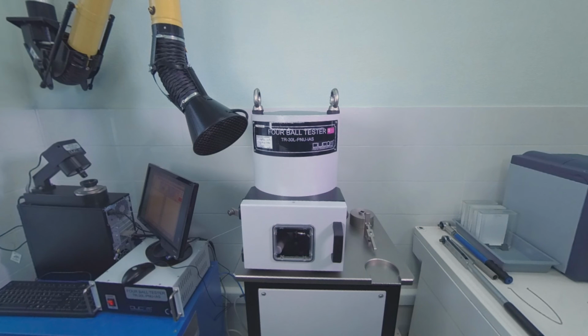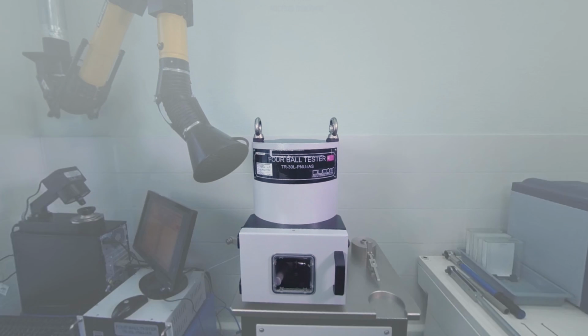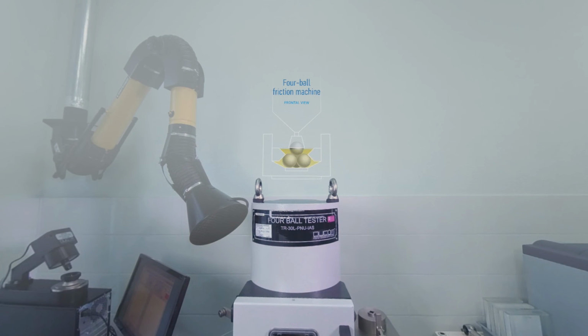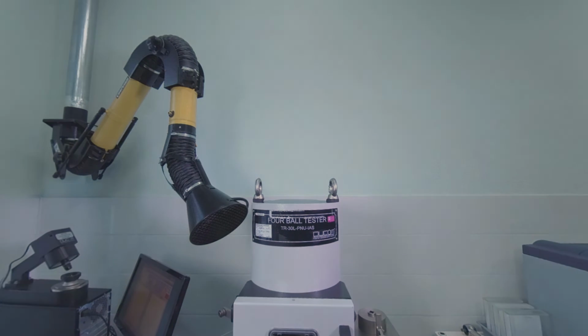Anti-wear and anti-seize properties of lubricants in the friction units under different loads and rotating speeds are determined by a 4-ball friction machine. 3 metal balls are tightly fixed inside, and the 4th ball rubs against them with a specified frequency and speed. The friction unit is filled with oil or lubricant. In a specified time, wear scars are formed on the balls at the points of rubbing. Better anti-wear and anti-seize properties of the oil mean smaller wear scar diameters and higher welding loads. This means better protection of equipment parts under real operating conditions.